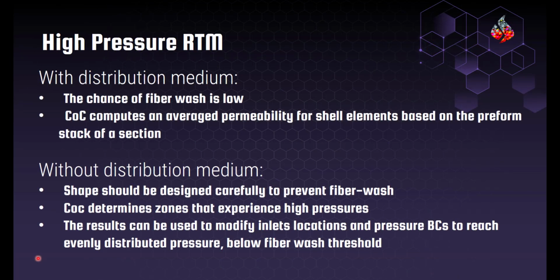In our brief search in the literature, high-pressure RTM is either achieved with a distribution medium, where the chance of fiber wash is low, or without the medium, where the shape of the part should be designed carefully to prevent fiber wash. In the former case, the user can create a stack of preforms including the distribution medium, and the total permeability is calculated as an averaged value for the whole stack.